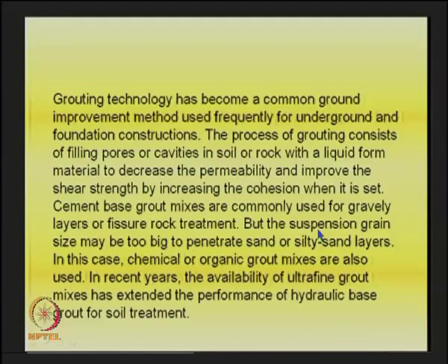It has to occupy all the voids. In some cases, when the grain size distribution of the soil itself is very fine, the suspension may not get into the system, and what we do is go for chemical or organic grout mixes, which are quite useful in those conditions.